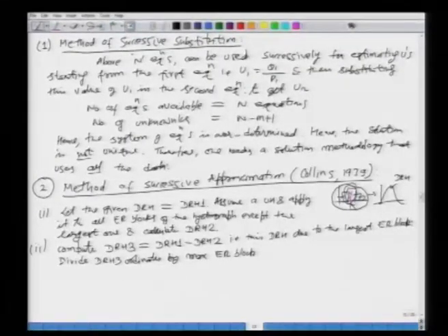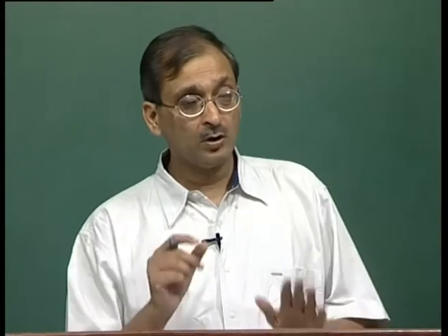If you do that, what will it give you? You have a DRH resulting from a certain amount of rainfall, the largest effective rainfall block. So, you divide that DRH by that amount of rainfall, what should you get? Well, the unit hydrograph for that duration, isn't it, by the principle of proportionality.